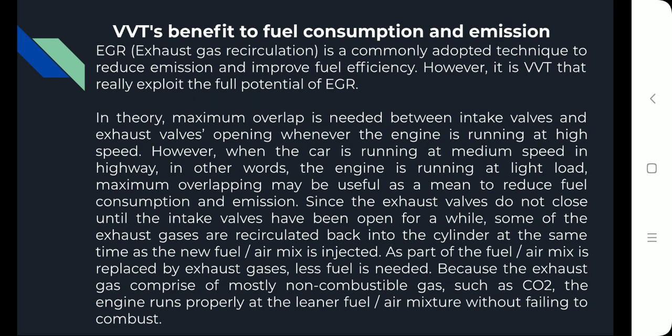As part of the fuel and air mix is replaced by exhaust gas, less fuel is needed. Because exhaust gas comprises mostly non-combustible gas such as CO2, the engine runs properly at a leaner fuel and air mixture without failing to combust.